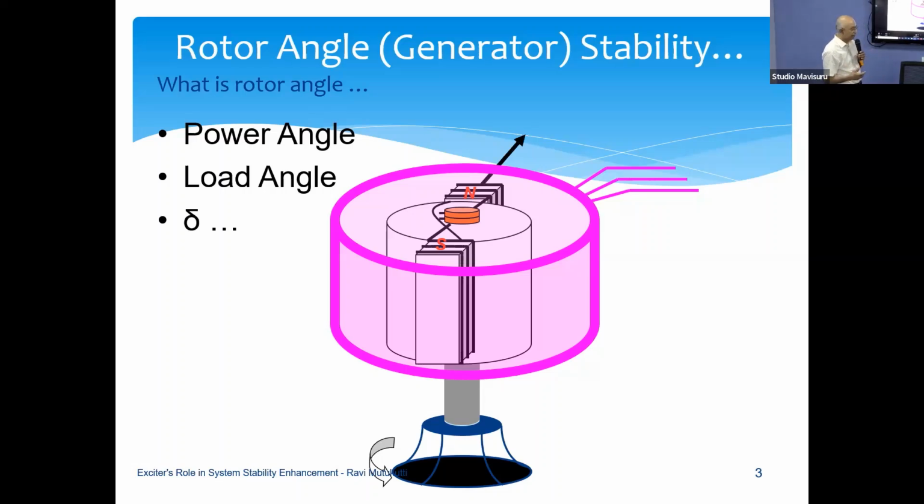In order to understand that, whenever you synchronize a unit, a synchronous generator has a rotating magnetic field in the rotor, which is driven by a turbine. Turbine could be a gas turbine, a water turbine or a steam turbine. So regardless of the prime mover energy type, you do have a rotating magnetic field. Any magnet has a north and south pole. Whenever the prime mover gets water or steam or gas, it is going to rotate the rotor. So while the rotor is rotating, you do have a rotating magnetic field. So we call it a rotating magnetic field.